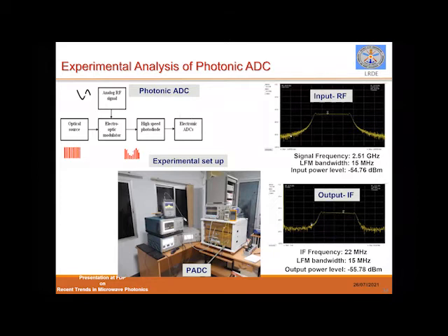So if you ask me, I can give a signal of 40 gigahertz directly to these blocks. This whole block is known as a photonic ADC in the open literature also. For example, these two are inputs. The photonic ADC is only this much, where there are two inputs, one is RF and one is the ultra short pulses from an MLL.